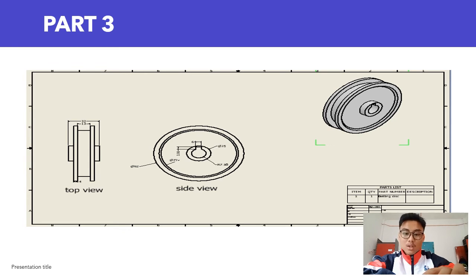First, I selected the XY plane to start the 2D sketch, and after the first sketch was done, I extruded it to build the body with a 77 diameter. After that, I made a sketch on the body. Then I made a hole using the extrude function to create a cylinder shape 32 millimeters long. For a small detail, I made the pinhole using the extrude cut function.